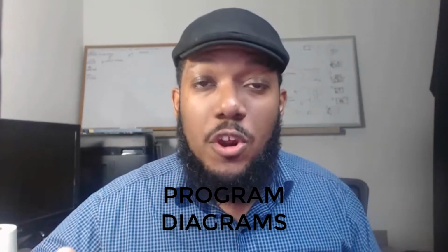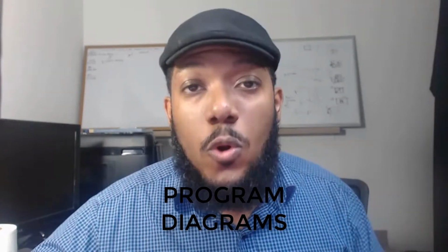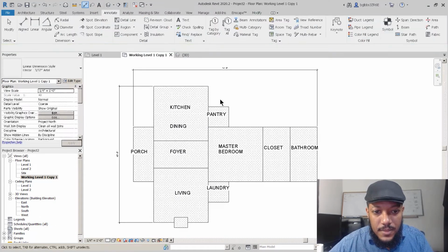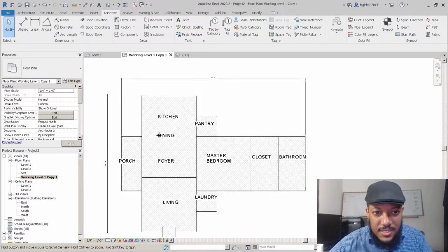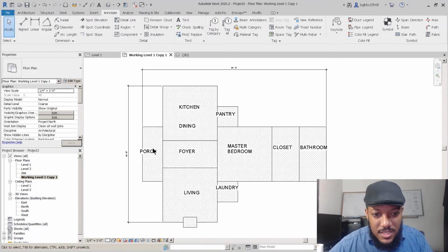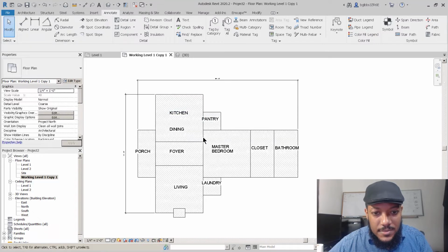I've made a program with some of the regions from working with the first parts of this plan, and now we're going to go from these regions into walls, roof, and a floor, so you can see the process. And we'll talk about families as we're starting to add in some of the elements that will make your model come to life. So we're still working in the working drawing, in the level called working level. You see the layout of some basic spaces that are typically in a building. So these are all just text over different regional masses.